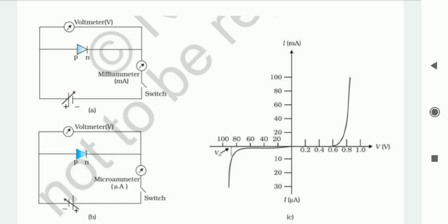diagram C. Now, if we connect the diode in reverse bias, then the generated current is very small, around microampere. Here the given reverse bias voltage is negative. Accordingly, in the reverse bias characteristic, the minus V voltage is on the minus X axis, and the generated current is negative, plotted on the minus Y axis. It means the reverse bias characteristic is available in the third quadrant.